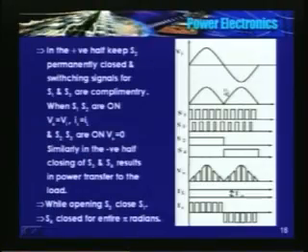So this is the control strategy. See, here are the waveforms. Input voltage Vi, I have rectified it. This waveform I compared with the high frequency triangular, had a large number of pulses.